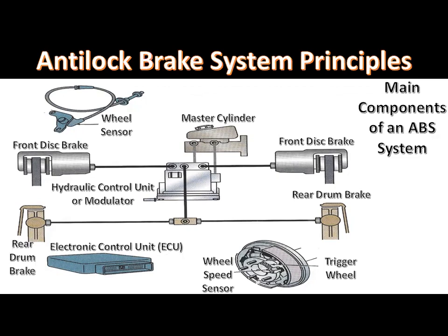If a wheel locks up during a brake application, the tire exhibits a loss of traction. Conversely, if enough braking force is applied that the tire slips to a certain extent without wheel lockup, a traction increase is experienced. This traction increase is highest at 10% to 20% tire slip on the road surface. If there is 20% tire slip, the wheel is turning at 80% of the vehicle speed. An ABS is designed to provide approximately 10% to 20% tire slip without experiencing wheel lockup during the anti-lock brake function.